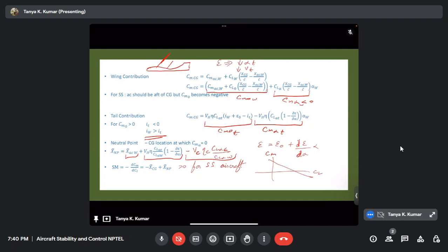Okay, all right. Another thing that we had seen was, where do I show this? Okay, so your Cm versus alpha has the same nature. Both these graphs, Cm versus CL and Cm versus alpha, will be of the same nature. What does that mean? They will both have a negative slope. Okay, but the Cm naught, or the intercepts, of both the graphs are different.